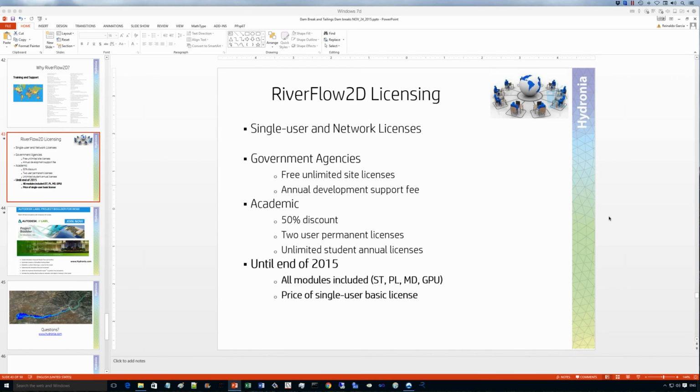Now, Flow2D is a two-dimensional model with uniform square grid elements, with only 8 different velocity directions at one grid element. So you don't have a full two-dimensional depiction of the velocity at the grid element level. RiverFlow2D is a full 2D model, and you can adapt the mesh very easily to any geometry. So I think those are the main differences between RiverFlow2D and Flow2D in regards to Mudflow and dam break analysis.